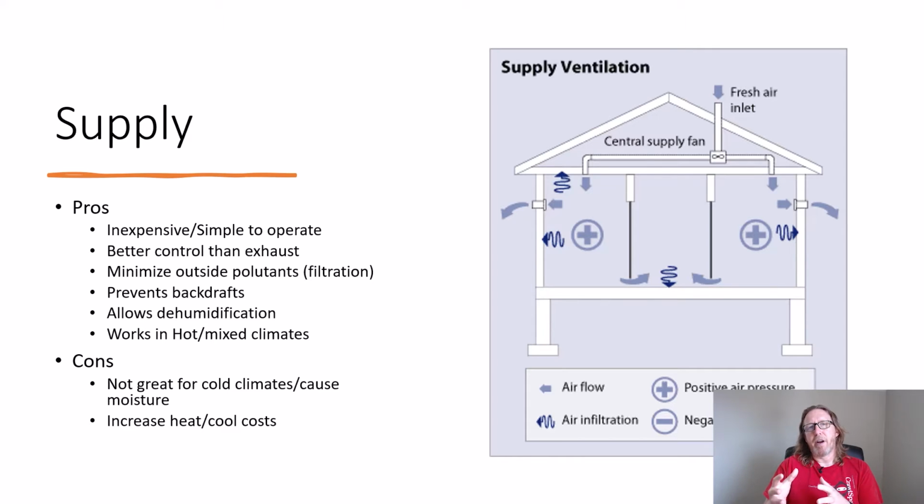Plus, dehumidifiers come with filters, so you're filtering and controlling humidity. Now keep in mind, some of these ventilators can open and close only when the humidity is not extreme outside, which means the dehumidifier does not have to work as hard. Some of these are smart enough that you can set limitations on when they open and close and bring fresh air into the home, which is nice.